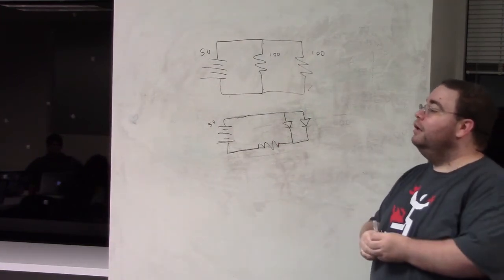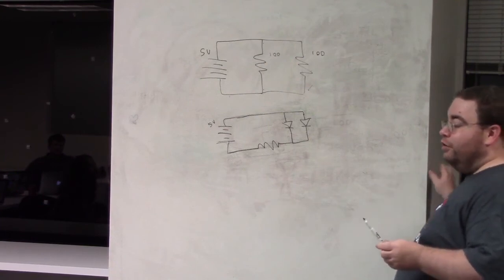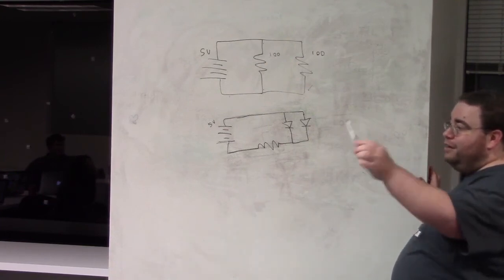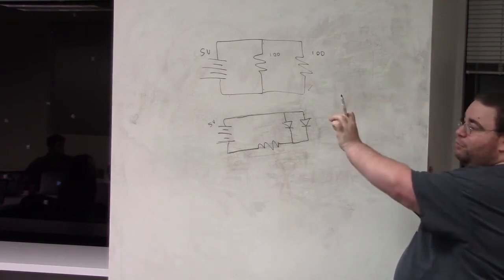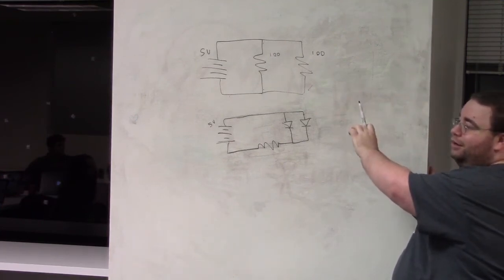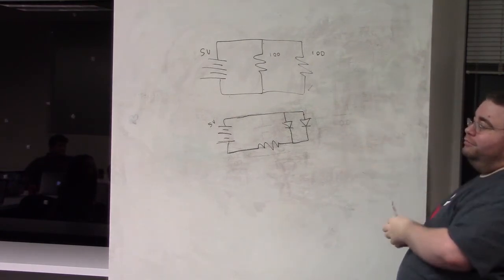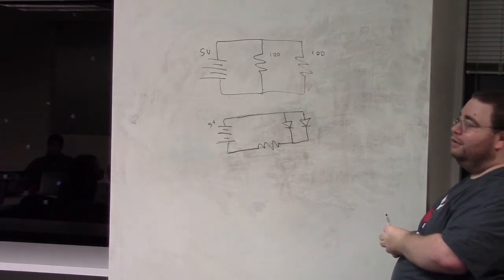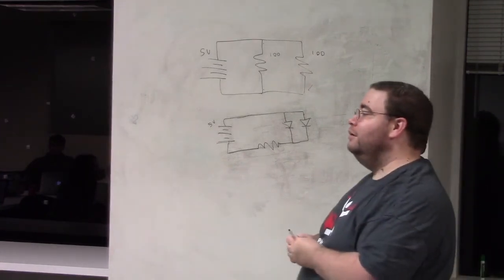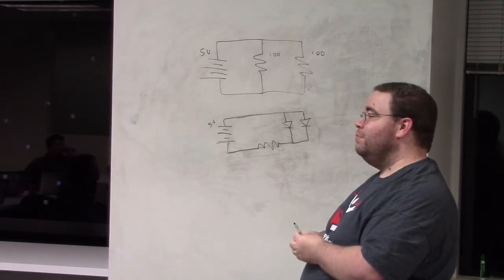Are they okay in series though? In series they are, except that, remember, they're going to light up based on what the voltage coming into them is. And so you're going to have one bright one, then a slightly dimmer one, then a slightly dimmer one, and so on. So the best way to do it is in parallel with one resistor per LED. How does it know? I thought the voltage levels were arbitrary. How does the LED know that its voltage is higher than the next one's?